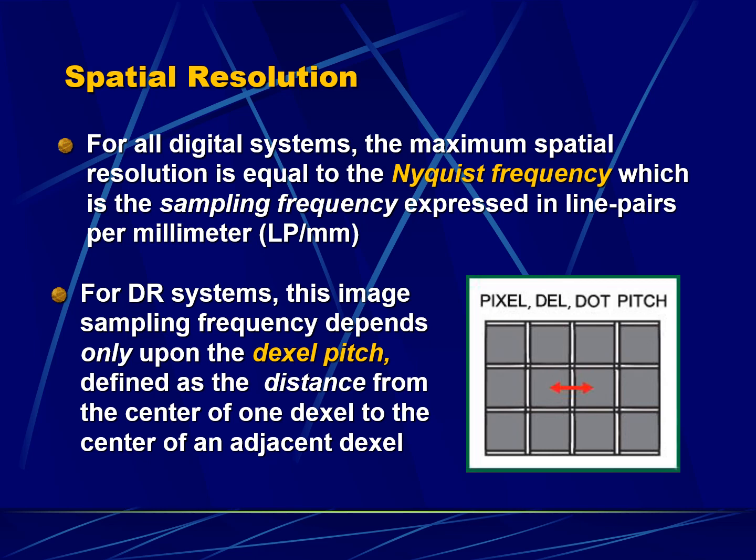Because when you convert from analog to digital, you don't use all of the analog signal. You take finite measurements at points on the timeline, and then you estimate the analog signal. Well, what Nyquist figured out is if you don't take enough measurements proportional to the cycle of the native wave of whatever it is you're trying to reproduce or convert from analog to digital, if you don't take enough sampling measurements frequently enough, then you get what's called a fold-over bias or an aliasing bias. Now, people who have played video games all the way back to the 80s are quite familiar with aliasing bias.